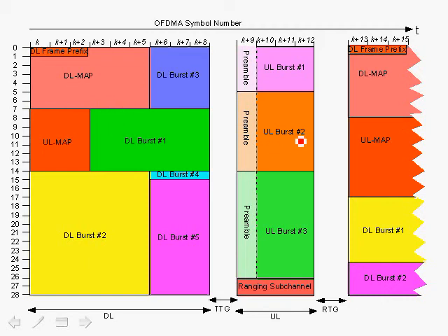This is unlike the case where we allocate pilots for transmissions from the subscribers during the uplink. Those pilots are done on a per user basis and their positions change depending on the allocation of subchannels, both the offset and the number of subchannels for that particular user. Of course, the base station has to track each set of pilots for a particular user on an individual basis.